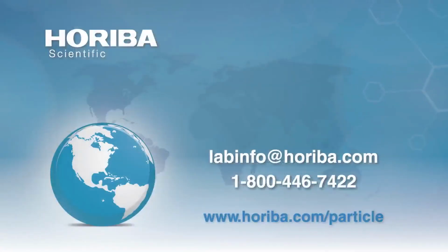The question here is, is there a single parameter that is a good indicator to distinguish the different size distribution of non-spherical particles? Yeah, I think what came out, I think you saw it alluded to a couple of places here. If we know that the aspect ratio is larger than about 1.5, then you know you're going to have an issue with this. If it looks like it's basically spherical, then you don't have a problem.